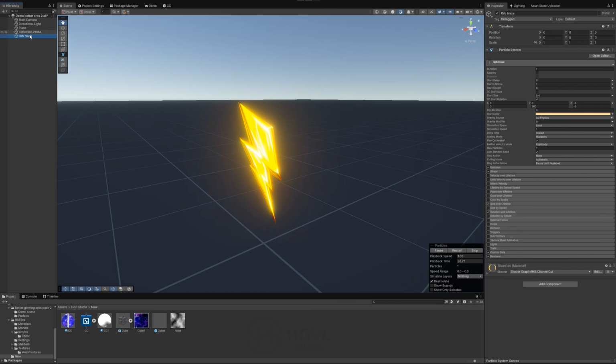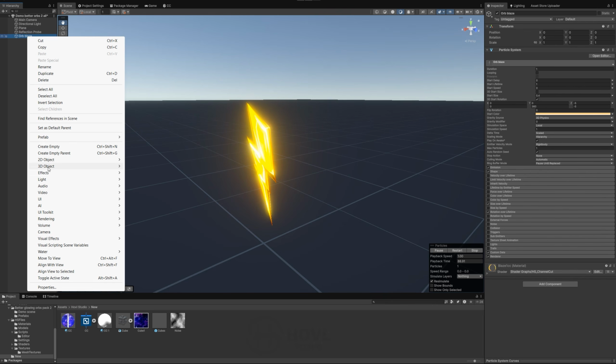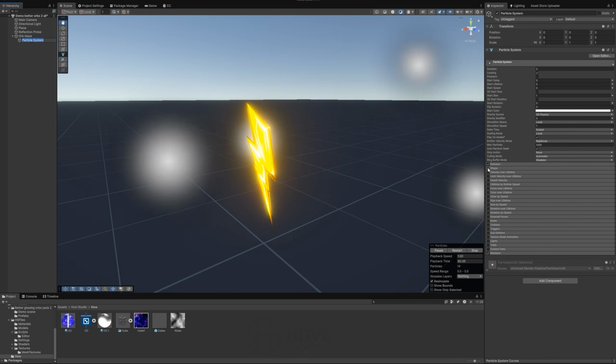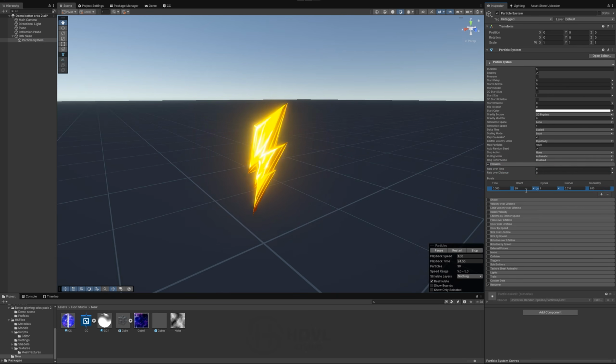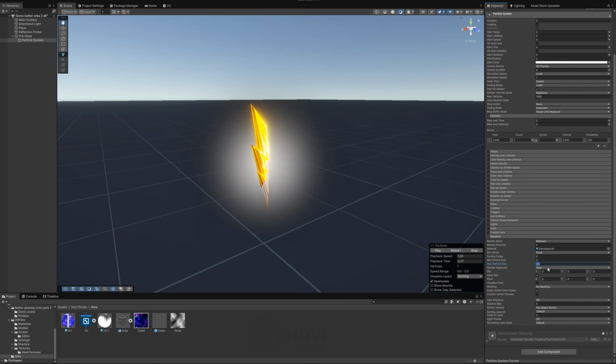You can also add a glow on the background. Just create a new particle system, disable shape, set burst 1 particle, disable speed, looping, and enable pause until replaced. Set size to maybe 4 and change max particle size to maybe 32.